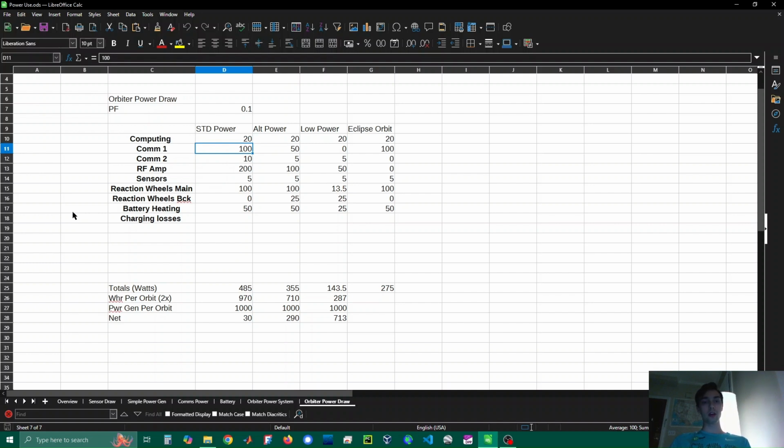And then our communication system. So COM1 in this case is our X band, but it can also be UHF. It's very flexible in its design. And the same with COM2. We'll also have multiple antennas inside the probe for high gain and low gain. You gotta create that redundancy because missions like Galileo truly prove that you need that.